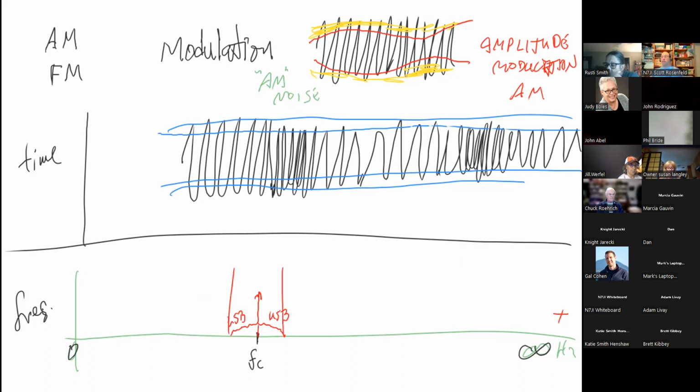What happens at that point is, okay, well, this is AM. We can now actually say how much bandwidth is taken up by somebody speaking into an AM voice signal. This is about 6 kilohertz. It takes up 6,000 hertz of space on the band. And we're talking physical, virtual space. How much room does it take up? Like if there was another signal that was right here, these would now be interfering with each other because they're overlapping. So we're going to make that other signal go away.